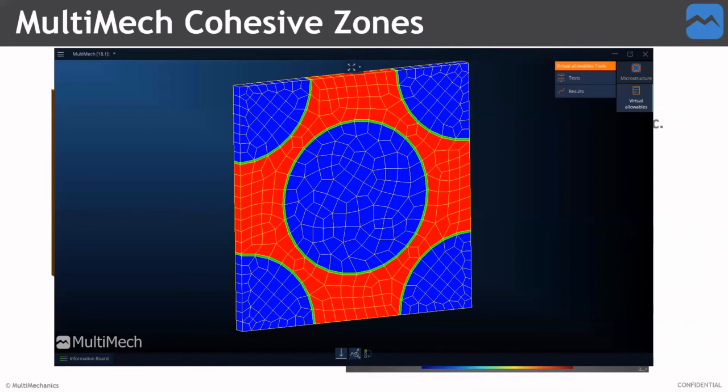And you can also go as far as saying, I want to model the fiber resin interface, which may not seem intuitive using a microstructure cohesive zone within a microstructure, but it's something that's completely capable within MultiMech, and we have seen people use this in order to even do a three-way multi-scale simulation in which we have a microstructure within a microstructure. Multi-scale inception, if you will.